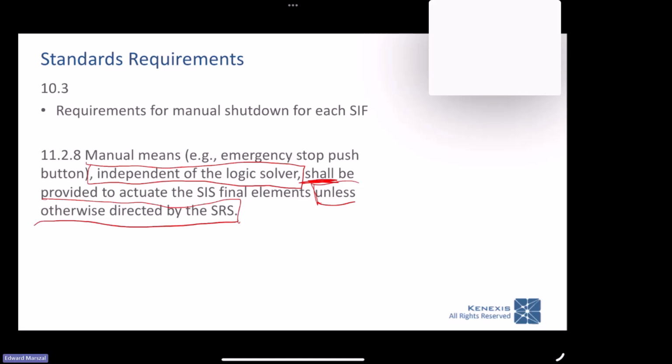It starts dripping on the PLC itself. And eventually, the water drips into the backplane and creates a short circuit. So, what happens when you short circuit an unsophisticated PLC? Basically, everything in the field is energized, and there's no way you can shut it off.